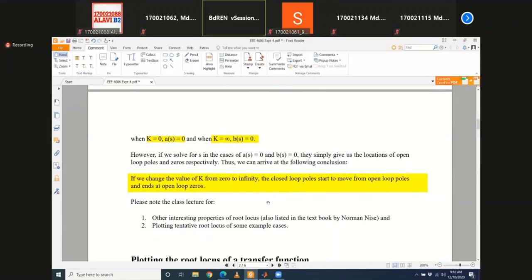So why do we want to do that? I mean, what advantage is there if we change the location of the closed loop poles by changing k? What advantage does that offer? We can make an unstable system stable. We can change various other parameters, right? Like overshoot, rise time. All of these factors depend on the location of the closed loop poles. You should know this, right?